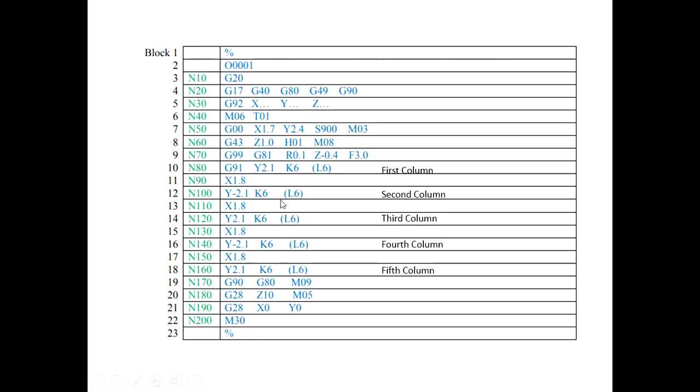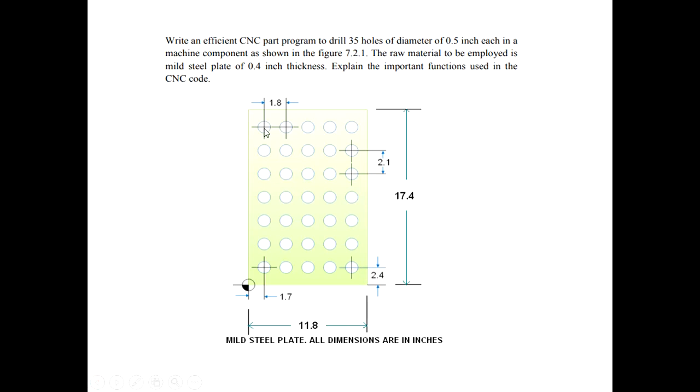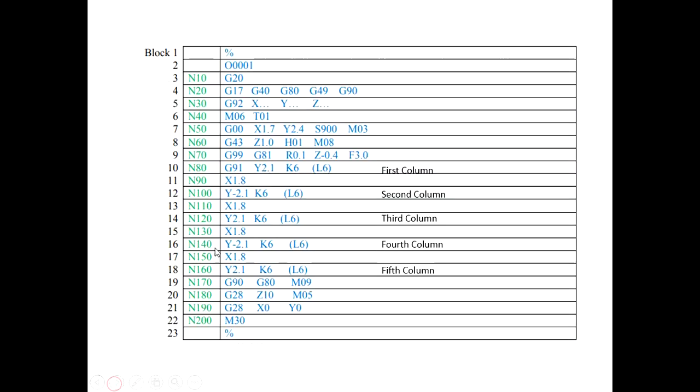Now you have to specify the X coordinate. X is what? 1.8. Okay, so after drilling the last hole, it will go to this position now. It will drill the hole at this position in the second column.